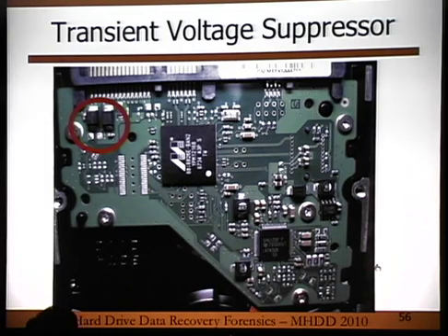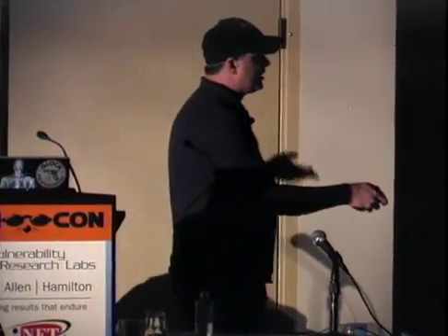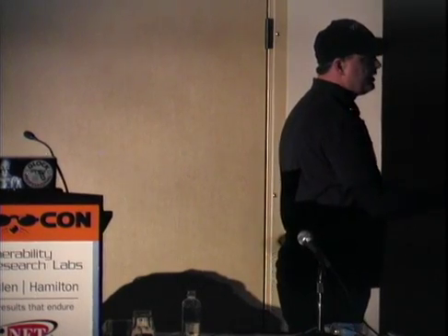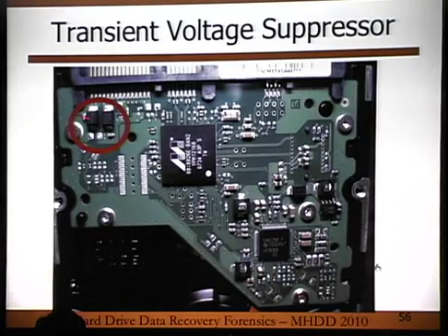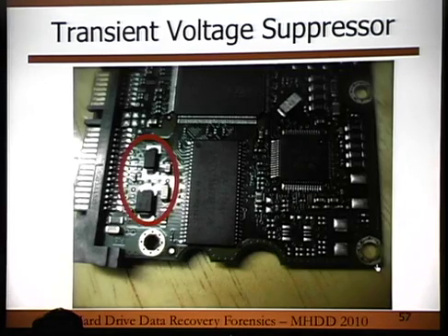Well, on hard drives these days, you'll find these on the bottom of almost all of your 3.5-inch hard drives. There will be these two fuses. Basically, these suppressors: the smaller one is 5 volt, and the bigger one is 12 volt. Now, I'm not just saying let's go rip these off, okay? But if you have no other alternative or you can't find a meter and test them, there is an option. It really won't do much damage. Almost all of these are near the power supply. So here's the power. Does it really get anybody that the power connector is a lot wider than the serial port itself? I mean, like, what the?